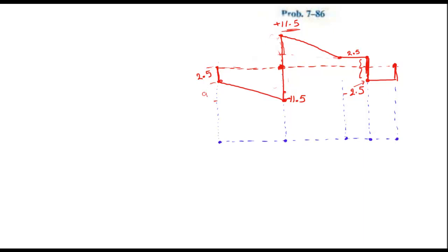Okay, let me try the green. How's the green? Yeah, it looks okay. So we have a roller here, or a hinge here, and we have a roller here. So the moment here should be 0, the moment here should be 0, since they are at the end of the beam and they don't resist any moments.